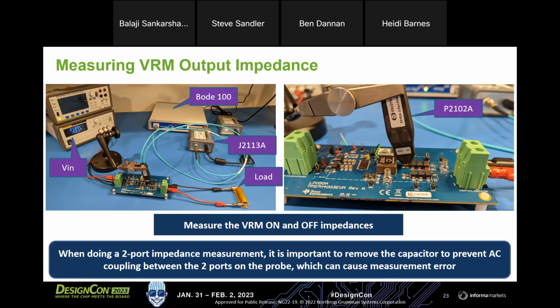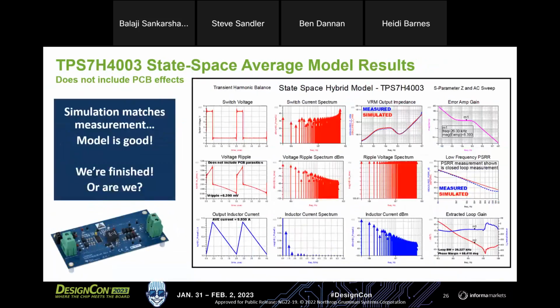Open loop is what it looks like with the power supply off, and closed loop is what it looks like with the power supply on. So if we have those two measurements, we can use those directly to solve for the loop gain T. But in NISM, the non-invasive stability measurement from impedance, it also helps us because there can often be a lot of peaks that show up in the impedance, many of them being high frequency passive resonances.